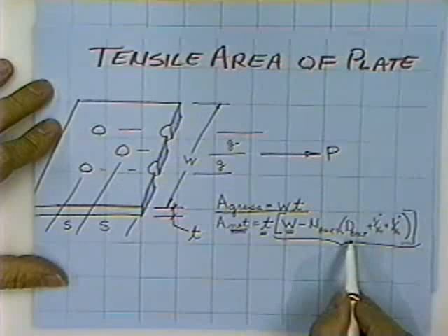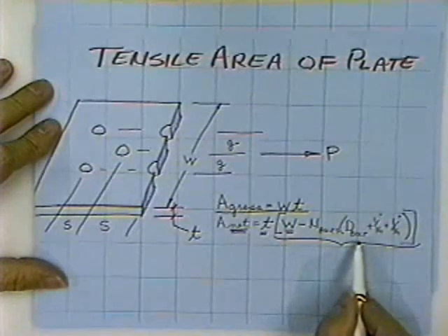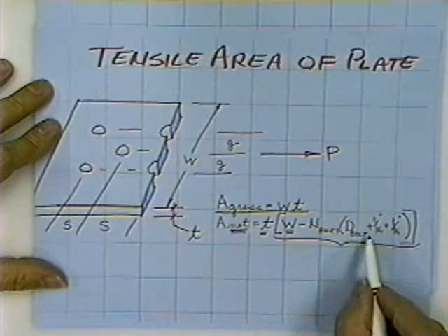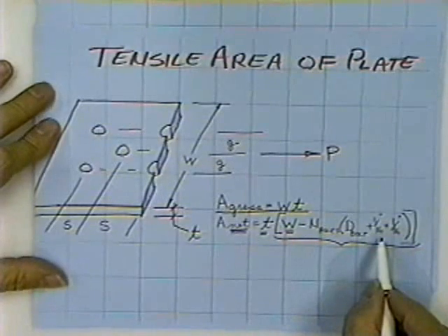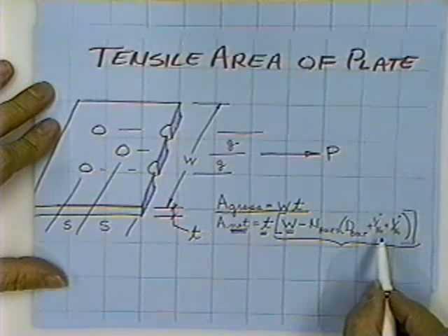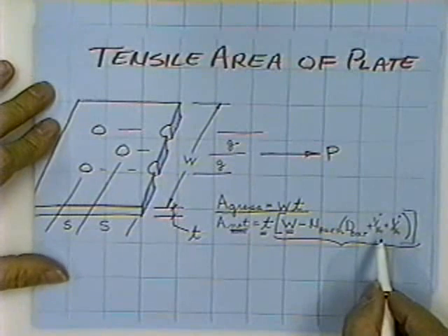And then the amount of steel that each hole removed is the diameter of the bolt to be used, and then they add 1/16 of an inch for fit, to make sure the thing will fit together, because when you drill these holes, they're never in the perfect place, and if you don't use a little bit bigger drill than the bolt size, you'll never get it together. Or they'll get it together, but there won't be any threads left when they get through banging them through those holes with a sledge.